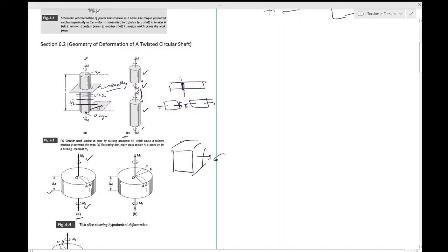that a sigma x stress cannot produce a gamma xy strain. So we had hypothetically deformed it, and then we rotated it, and then we said, well, this is contradicting something, and hence the only way this is possible is when gamma xy is 0. So you remember that? That was a hypothetical deformation which we assumed, and we are using a similar idea over here.